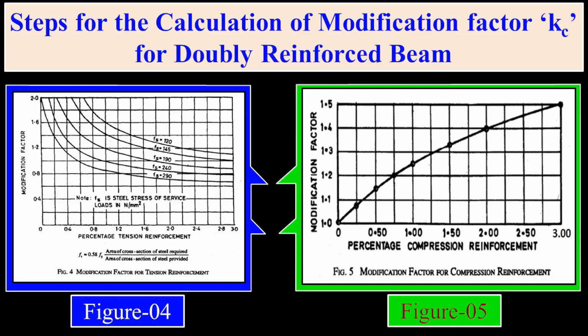If we find that this calculated effective span is greater than or equal to the actual effective span of our beam, then and only then can we say our deflection check is okay. Otherwise, we will have to alter our design parameters to satisfy the deflection criteria.